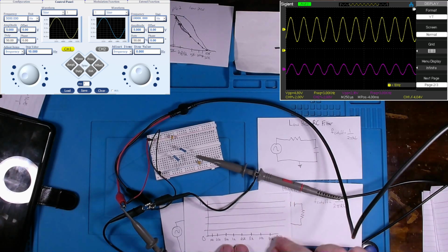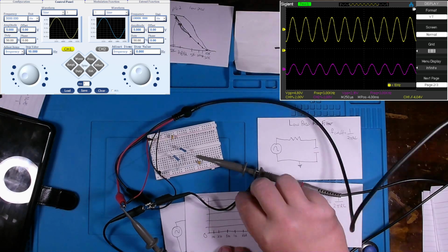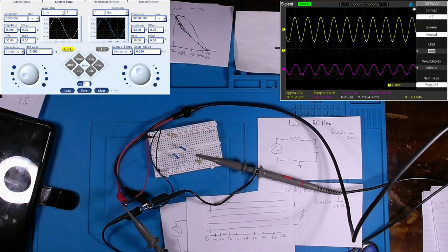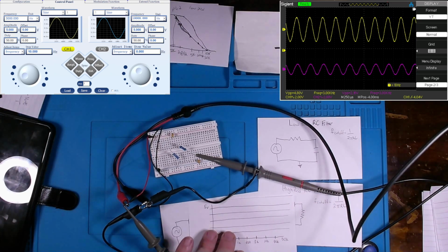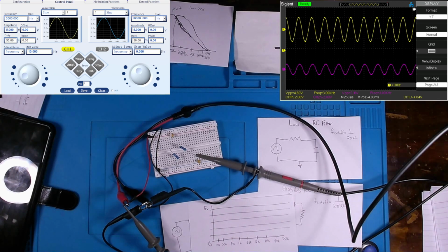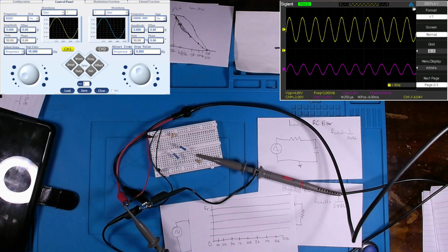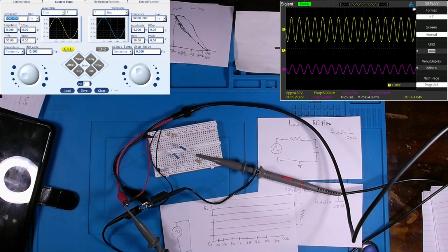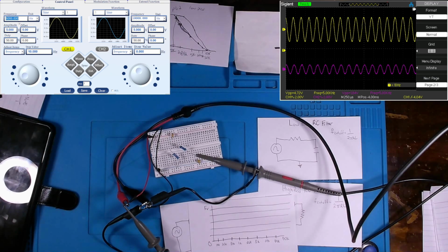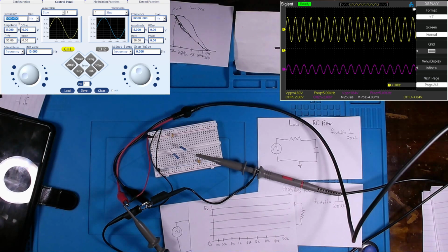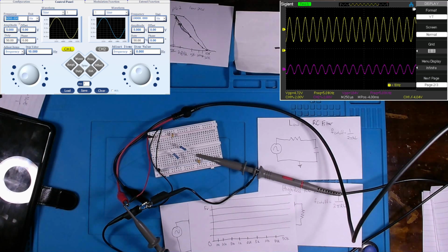And what I went ahead and did, developing my own graph here, a Bode plot, and you can already tell the difference right off the bat, is we'll start at 5K, okay? And at 5K, we have 1.84 volts.